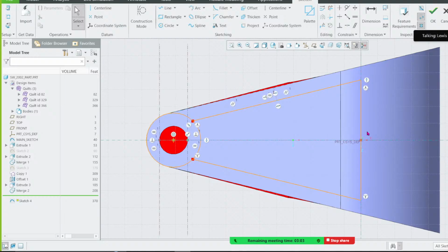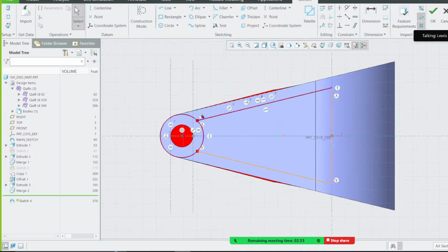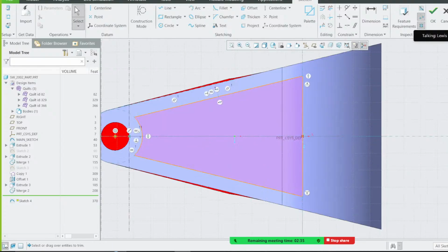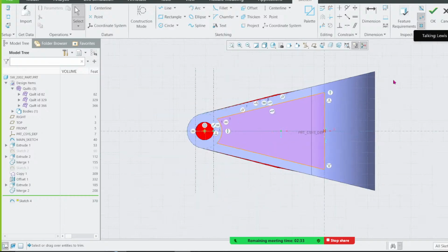I have another sketch, no dimension. I'm not dimensioning anything in my sketches. I'm just referencing, so that when you change something on top, nothing is going to break down the tree. Things break when you start dimensioning, when you perform double dimensioning. Lastly is about that. My sketch is fully defined. There's no dimension in my sketch.